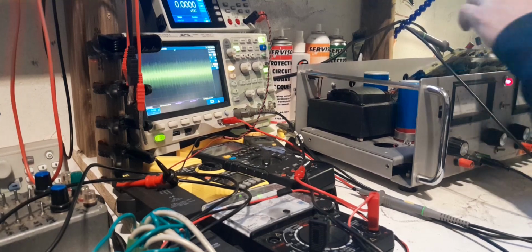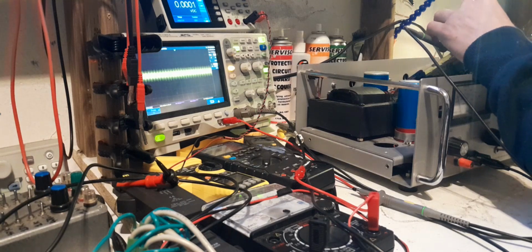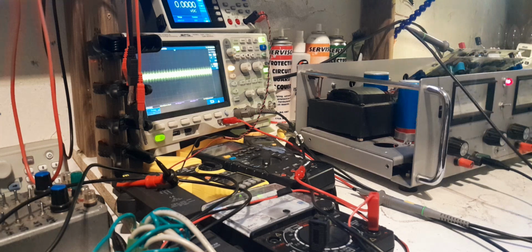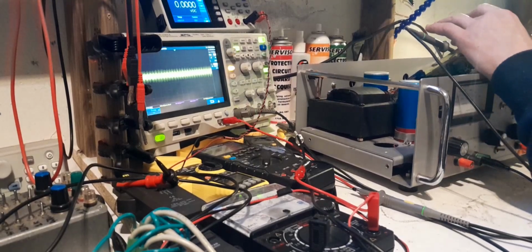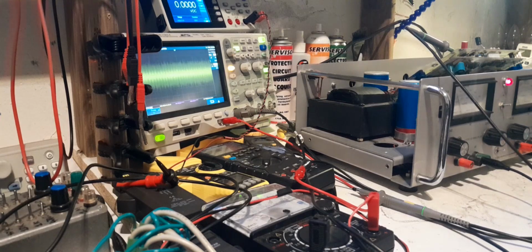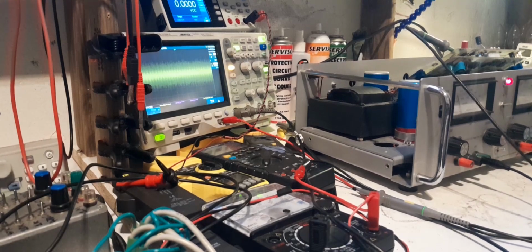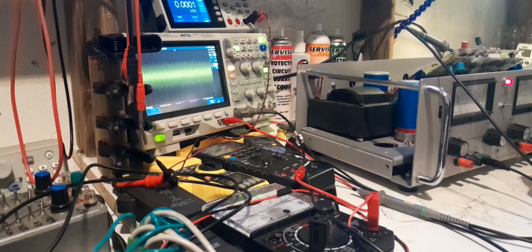Right, so with the cap, we drop down to 2.7-ish millivolts, 2.75 RMS, and around 20 to 22 millivolts peak to peak. So about half. And like I said, that's taken a whole 1 microfarad from the output, sorry, to the non-inverting input, which is, you can't just go sticking figures like that on op amps. So, next thing.